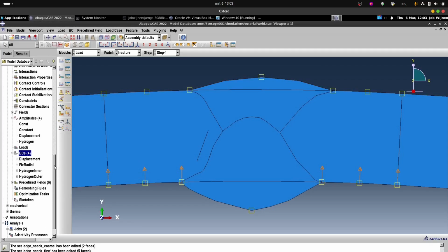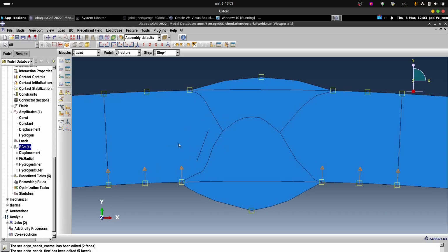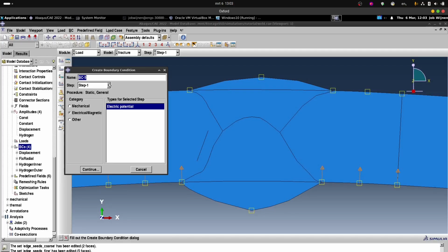Then there's one final boundary condition that we need to apply, and that's actually the crack itself. So we want to set basically the order parameter of the phase field model to 1 on the crack over here. So let's create another boundary condition. And similar as with hydrogen, there's initially no degree of freedom for the order parameter in Abaqus. But the easiest thing to do, which will later be automatically converted with the pre-processing scripts, is to choose the crack, prescribe that as a mechanical rotation actually.